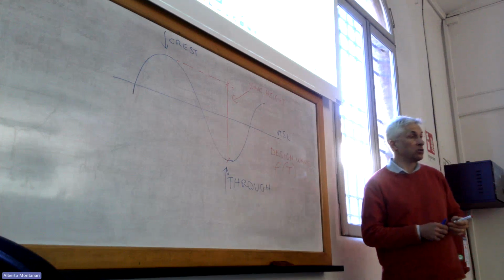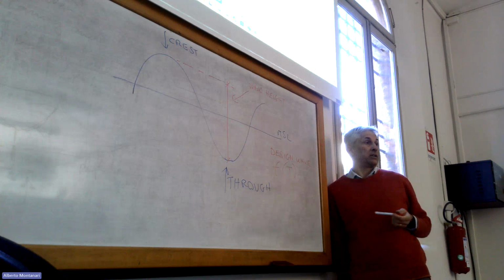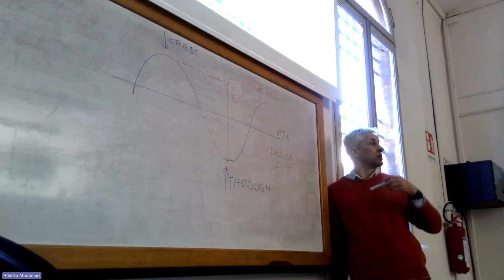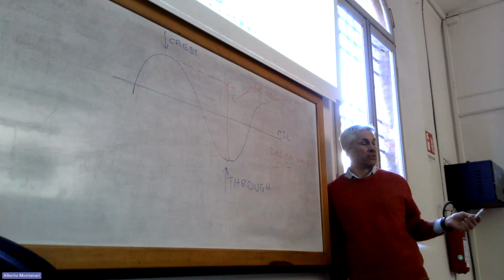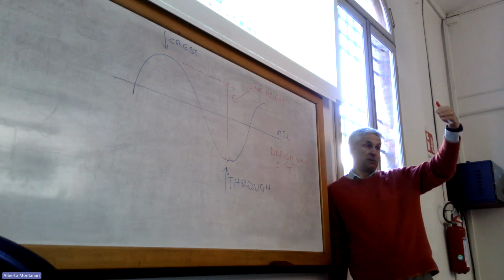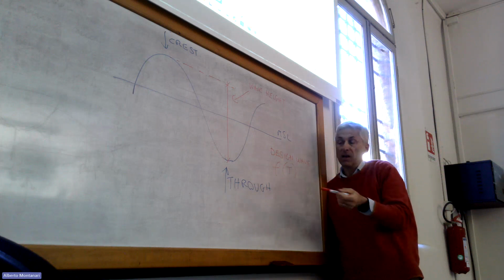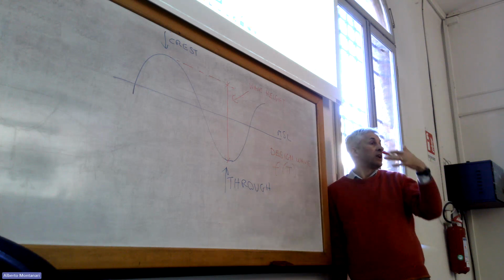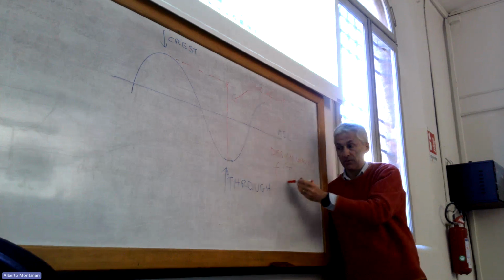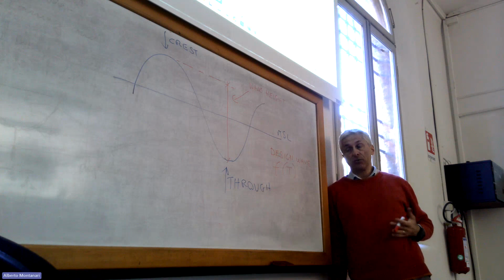Usually guidelines and rules give us the return period, and we discussed already the typical return period for structures, for berths, and for mooring lines, fenders, etc. We said that based on the life expectation of what we are designing, we are given the return period of the design. Okay.